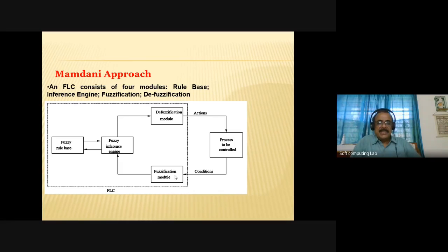Now, the rules are made ready, all 16 rules are made ready, and depending on the set of inputs, whenever we are passing one set of inputs, out of those 16 rules at a time, there could be a maximum of 4 fired rules. And for each of the fired rules, I'll be getting some output.